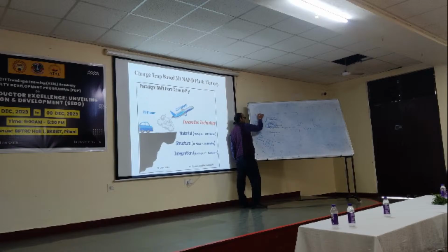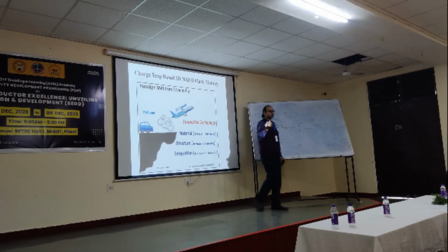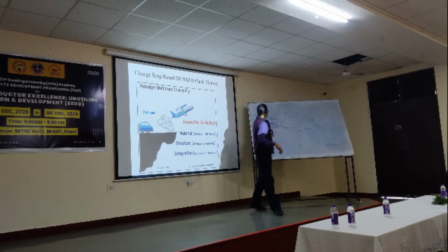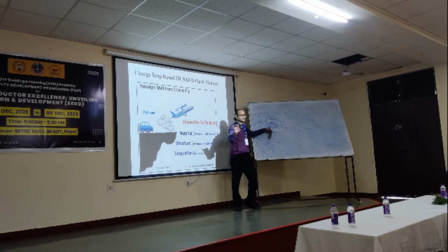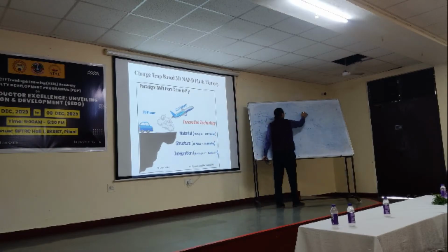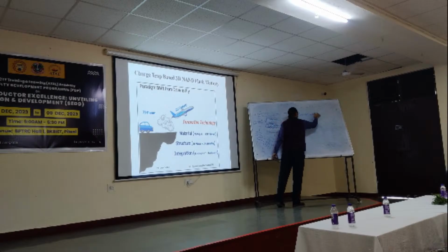Okay, and we call it a floating gate, a floating gate transistor. So why floating? Because this is not electrically connected to either the substrate or the metal. That's why floating. So this is the principle of operation of my research topic that I have done so far. This is a very basic structure. I hope you got that. Now, this is called write operation. This is called write operation, and I will also call this program.